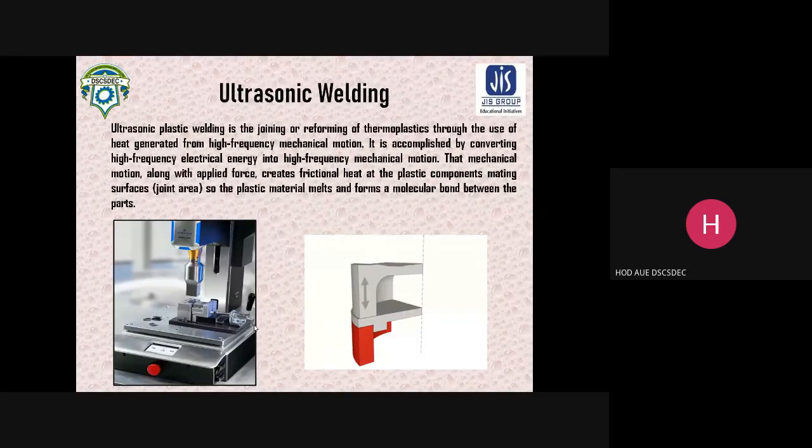This mechanical energy is creating the vibrations, and this mechanical motion along with the applied force creates frictional heat at the mating surface of the plastic components. So that plastic material melts. Generally this word melt is not correct, because melting is not done in case of ultrasonic welding.